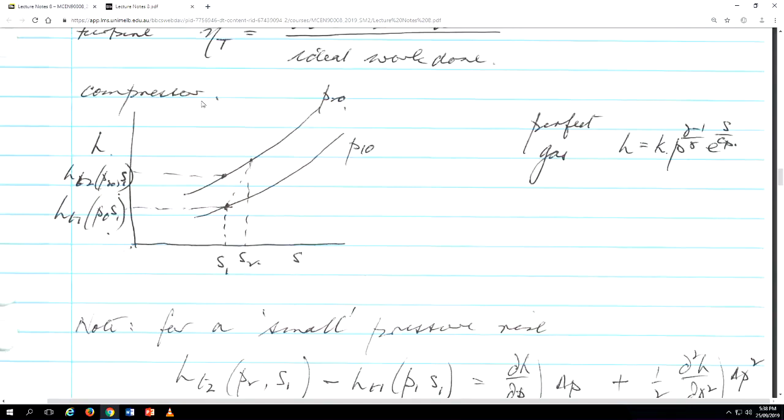So this is a Mollier diagram. H is a function of S, and P is P of these lines. And so we start here at this entropy, and actually our reservoir conditions, P1 naught, is right here, and the total enthalpy corresponds with that.